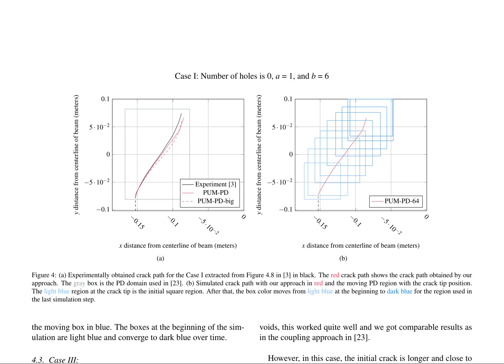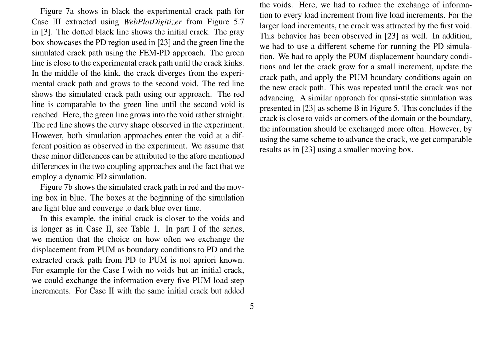In case 3, the experimental crack path is compared to simulated crack paths using both the FEM-PD approach and the author's approach. Figure 7a shows that the FEM-PD approach closely follows the experimental crack path until the crack kinks, whereas the author's approach more accurately captures the curvy shape observed in the experiment.